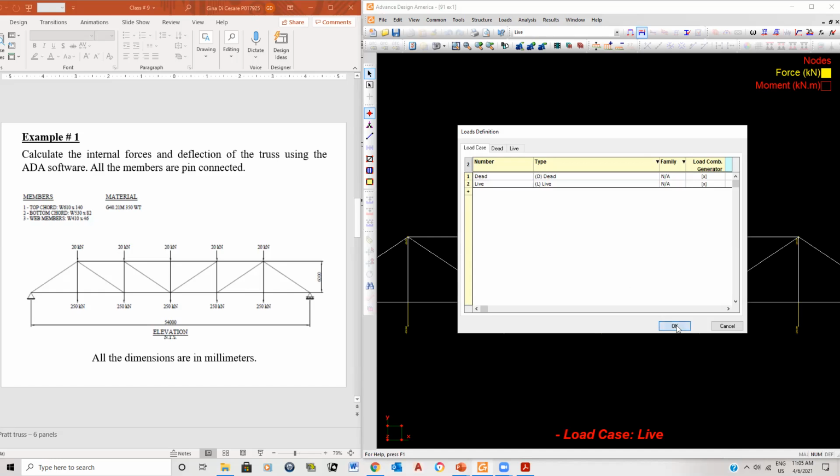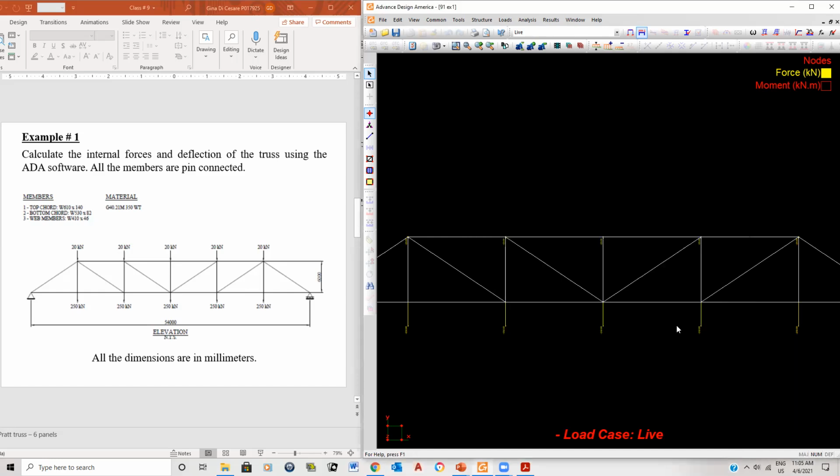So I activated the wrong one. I activated a load combination. Exactly. You don't even have a load combination yet. Well, I created it. But you shouldn't. You should work in the right steps, because it's useless for you to do your load combinations without doing your load cases. It's useless for you to do your loads without doing your model. You understand? So everything follows in a sequence.